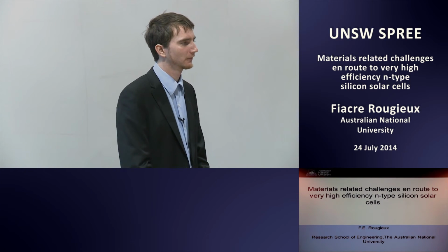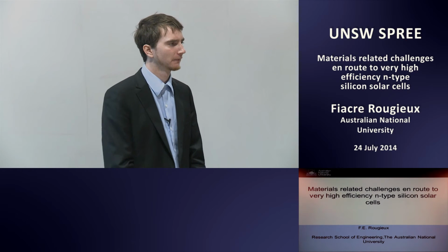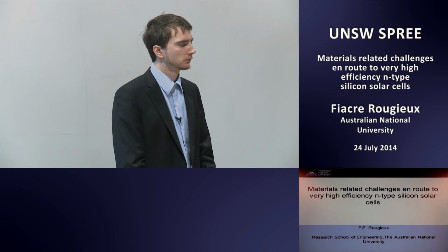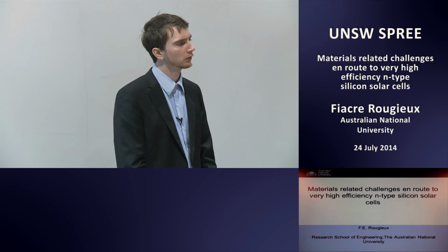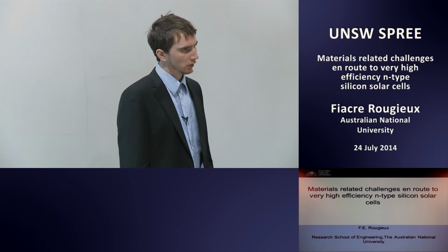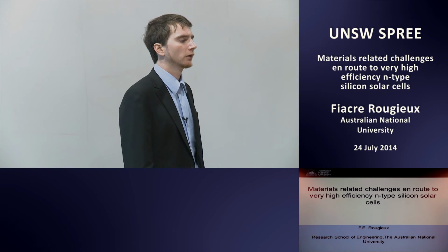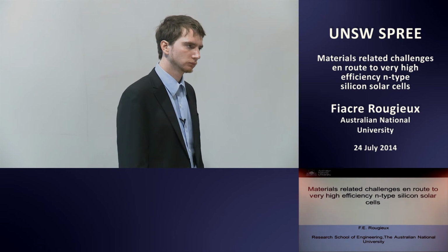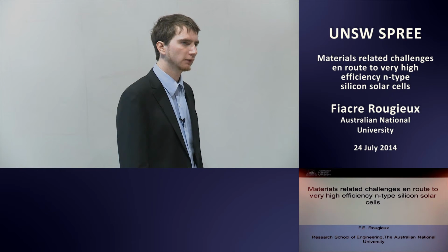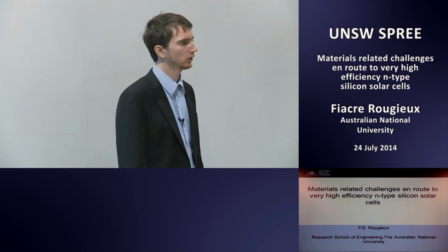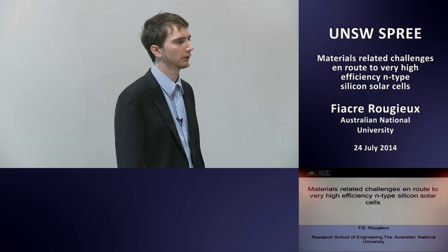Yes, I've got two questions. First one is, what are the anneal conditions that you have? Is it just nitrogen? Yes. You're talking about the float zone silicon? Yeah. For the float zone silicon, it's 1000 degrees in nitrogen, 1 hour. And how about the CZ one? Yeah, the CZ was also a nitrogen anneal, half an hour, above 360 degrees, yes.